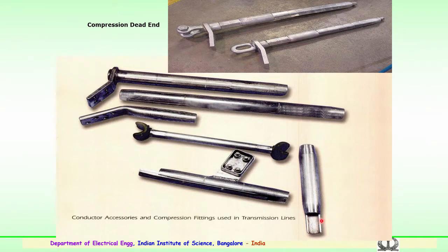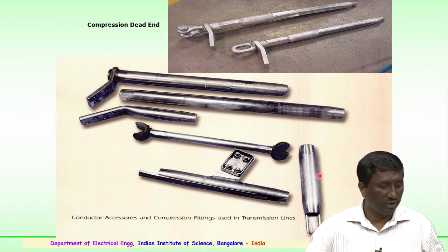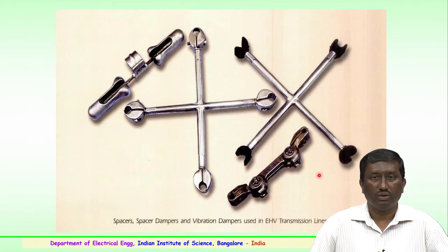Similarly, we have several very important conductor accessories which are used for transmission and distribution. You have terminating or end clamps, dead end clamps. You have the mid span compression joint, which helps to join the 2 conductors to continue the transmission lines. This is again a spacer to keep 450 distance. Then this is the T connector, and this is the repair sleeve in case the conductor gives away some strands, so it has to be properly repaired. This repair sleeve will bind the conductor at the junction where the conductor has become weak or needs repair. So, these are various spacers.